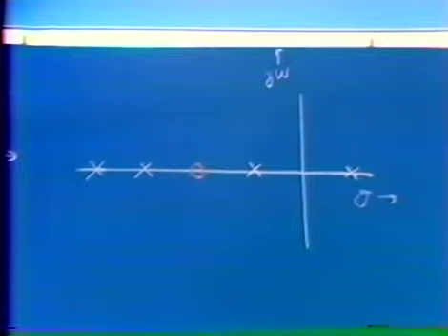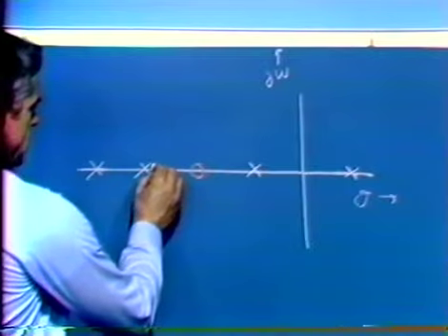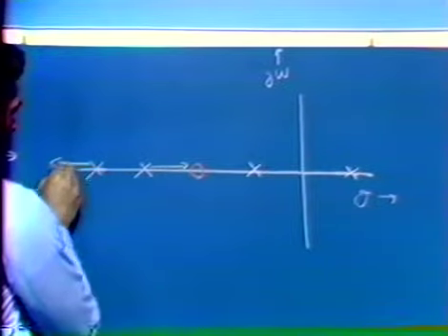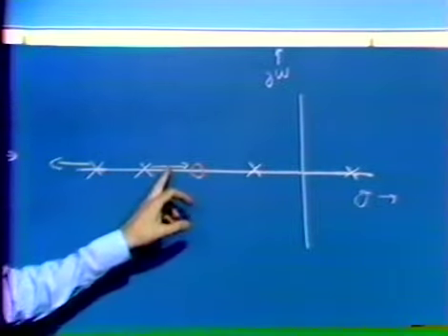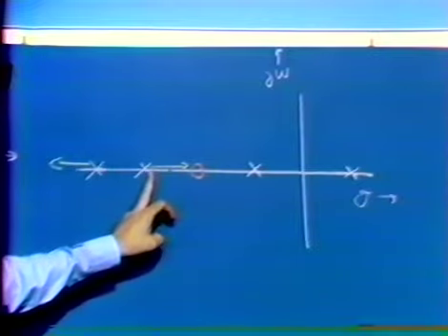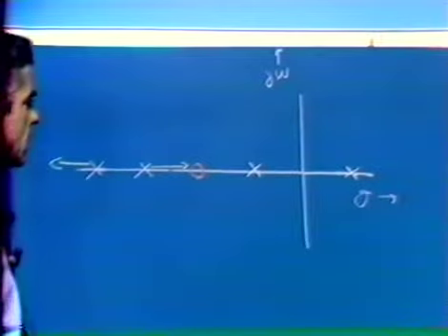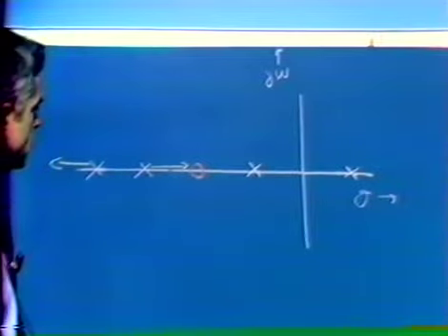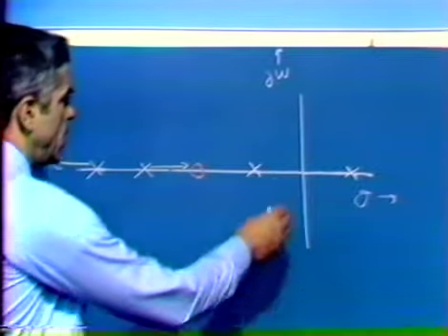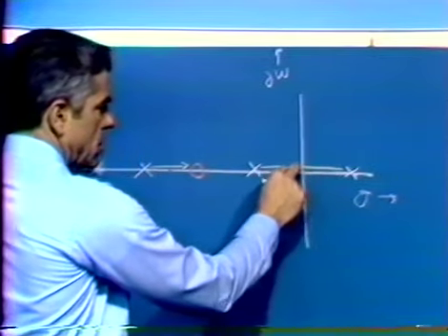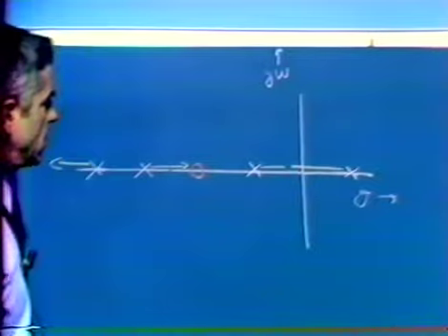stabilize the system. And if we've satisfied that condition, the root locus diagram for this thing looks something as follows. There's one branch that starts here and moves to the right, goes to this 0. This branch goes outward. However, this is a more remote pole, and so initially this pole closer to the origin has more influence on the behavior. Since that branch is moving to the right, this is a system where the average distance rule holds. Since we have 4 poles and only 1 0, the average distance of the poles corresponding to these branches must move somewhat to the left.